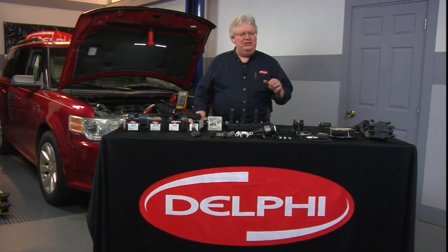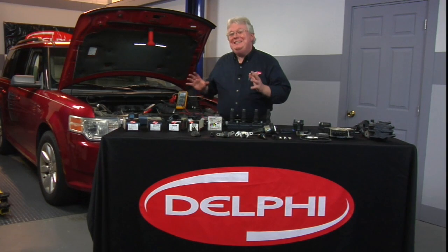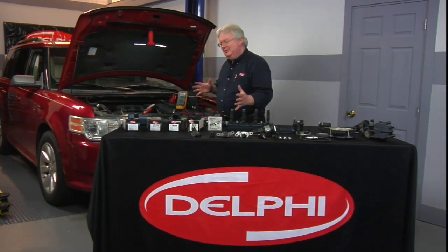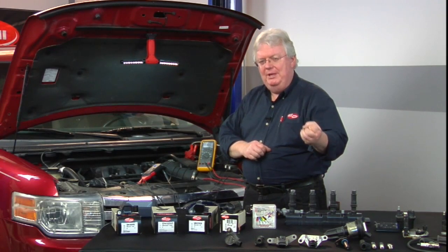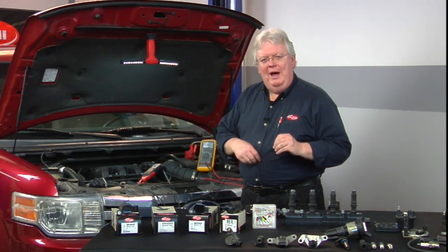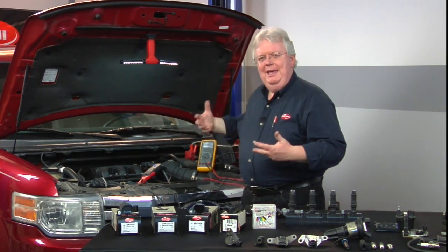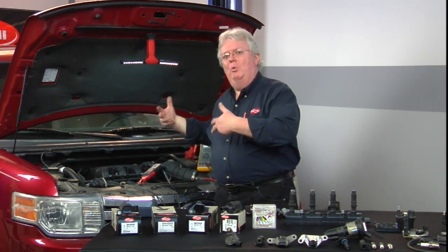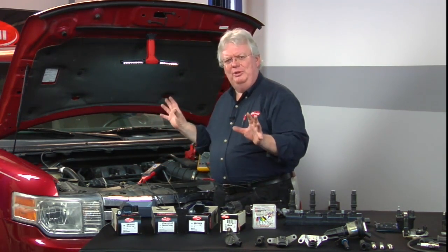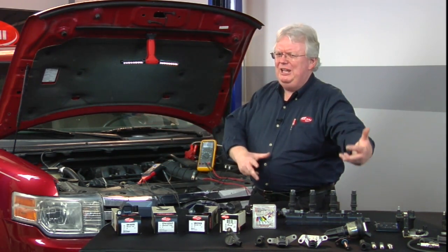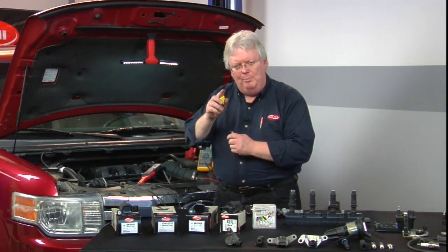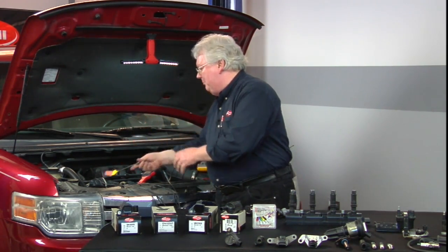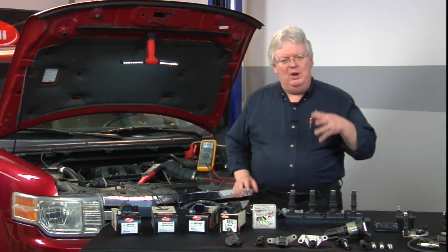There are technicians that could, back in the day of the big box analyzers, when you had one distributor, very easily hook a pattern clamp pickup around the coil wire, and then a signal pulse or a trigger lead off of some like number 1 plug wire, and see all the cylinders and all the events. This is going to be a little bit more work because you're going to be moving your back probing, moving your little secondary paddle pickup, if it works on that particular style of coil, around and watching things.